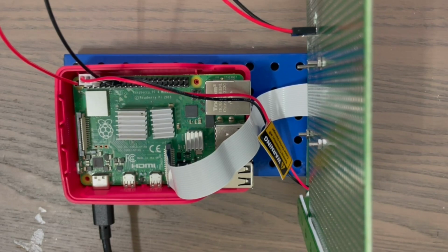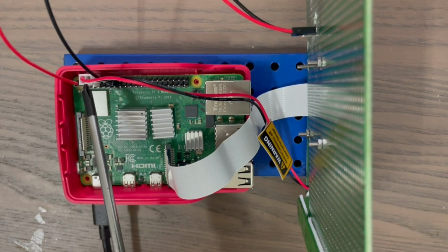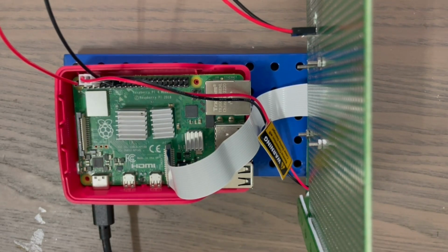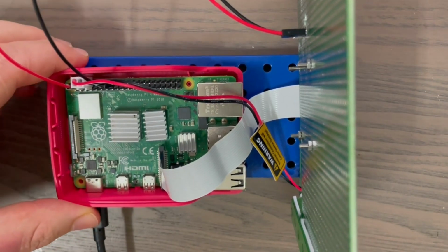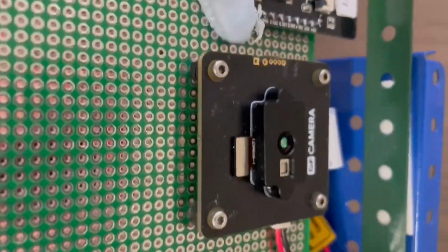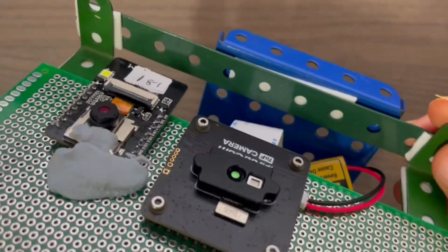And so that's what I've done. So I've connected an ESP32 cam up. So I've got the ESP32 cam just connected to the 5 volt and the ground of the Raspberry Pi. And this 5 volt and ground of the Raspberry Pi is connected to the Arducam time of flight camera. And then I'll just show you. I've got both of these, can you see that? I've got both of these mounted on this piece of perf board at the front.